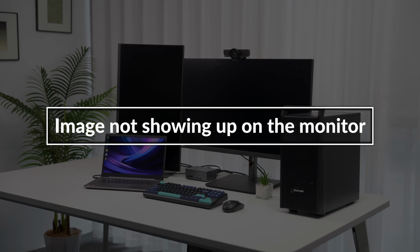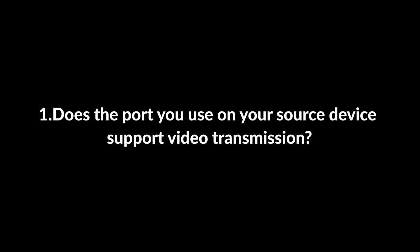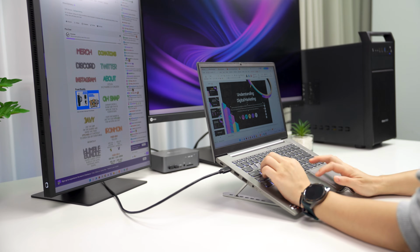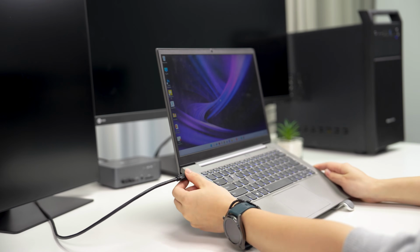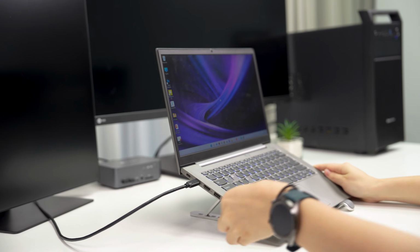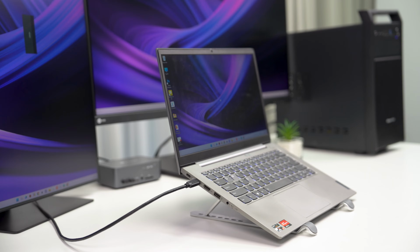Image not showing up on the monitor. Here are 5 things you can check. Number 1. Does the port you use on your source device support video transmission? Some laptops may have 2 Type-C ports on the side. One is only for charging and does not support video output. If you use it for video output, you won't get anything showed on display. Make sure the port you use supports video output.